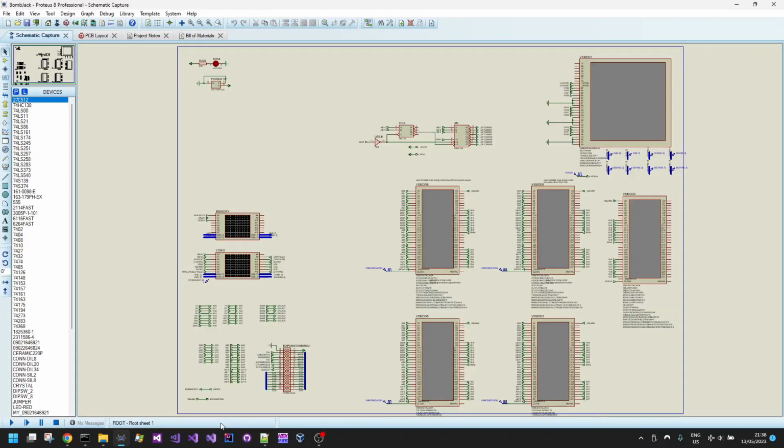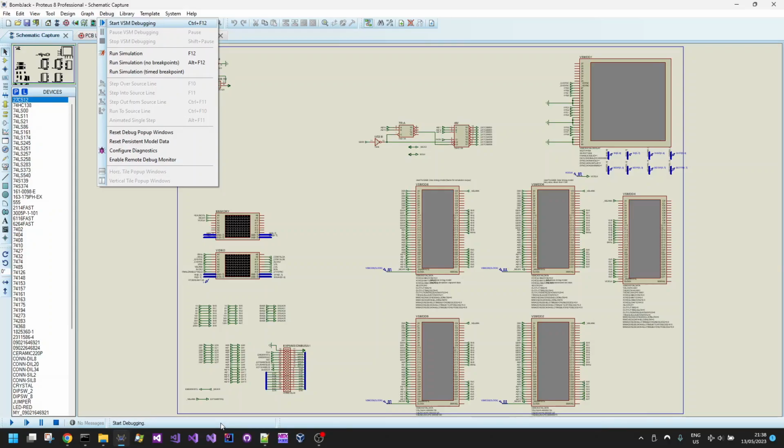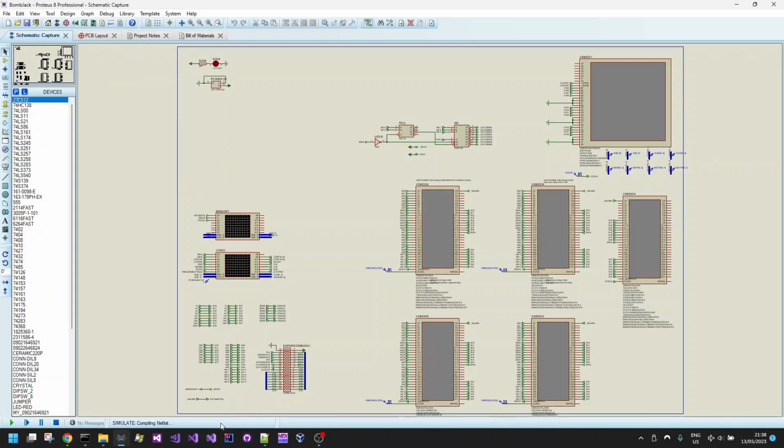The video hardware, which is the main BombJack project, actually comprises over 400 integrated circuits across all of the layers. So it's a normal sprites layer, a characters layer, a tiles layer. The characters are 8 by 8 pixels and the tiles are 16 by 16 pixels. And they have different virtual screen sizes which can scroll.